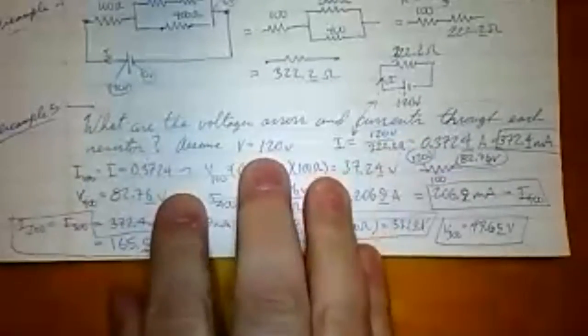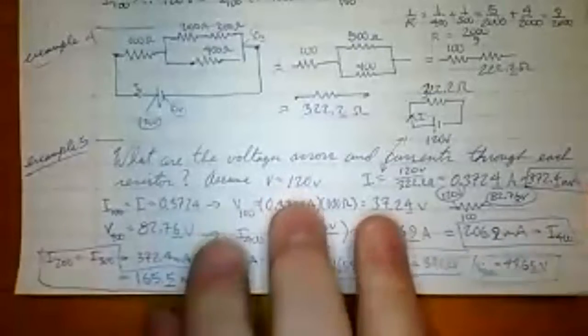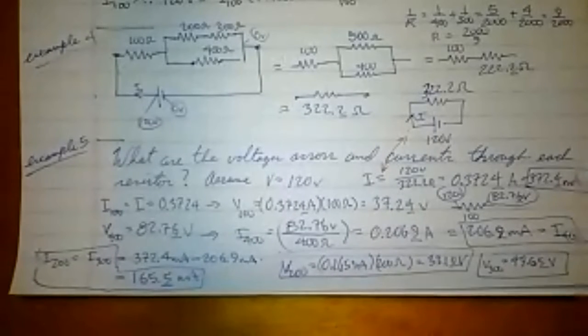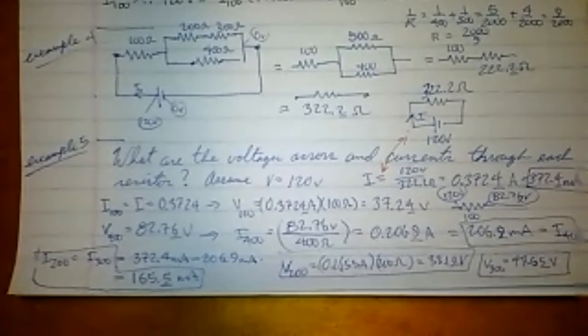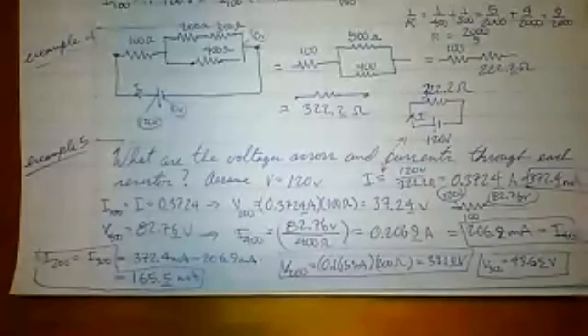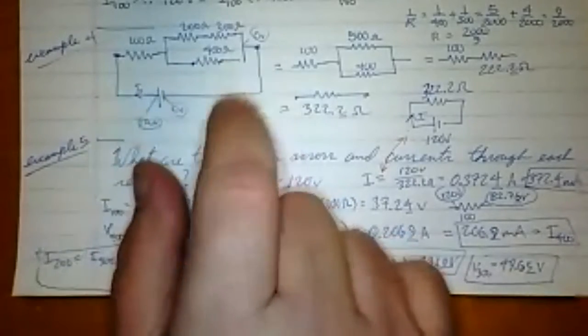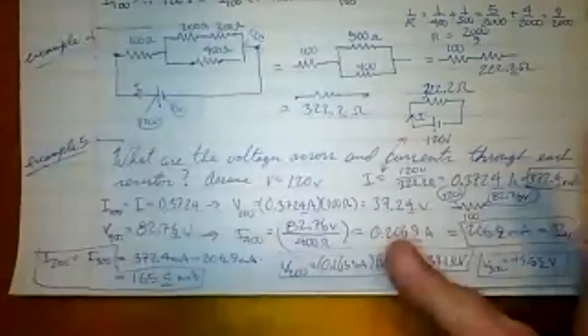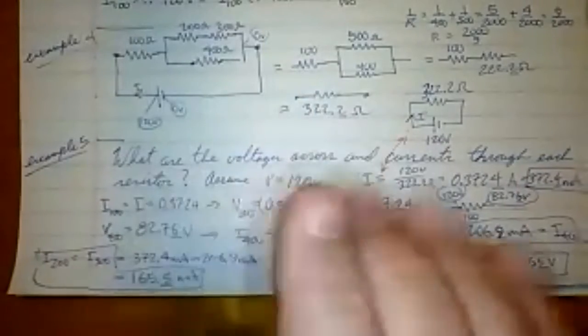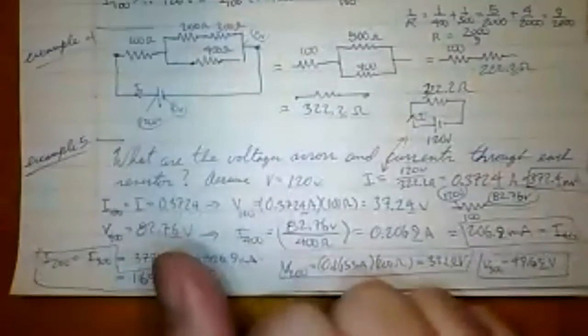Let's go back over and just talk about what we did. Maybe sum it up so that it makes a little more sense, because there's a lot of steps in that. And you don't always have to do it this way. In this case, I just sort of brute force tried to muscle my way through by understanding how voltage changed across resistors. Namely, if you go in the direction of the current, the resistance is going to represent a voltage drop. And then going from a short plate to a long plate on a battery makes a voltage increase. And I know the net voltage increases and decreases around any one loop is always going to give me a total of 0, because I step up, and then step down, and come back to the same height.